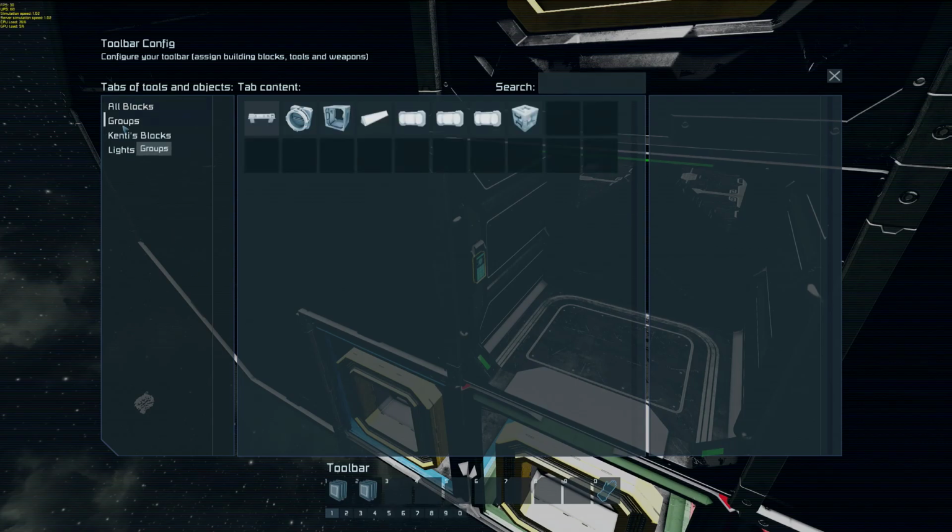So groups, in this case, we understand here warning and illumination. I'm looking for warning and illumination. So my red lights and my yellow lights specifically as groups really don't matter, even though I created groups to do that. What I actually did was took the two groups, put them together in one group, but there's a 50% offset on one versus the other. So it's really all within one group. I could delete those other groups and it wouldn't matter at all, but we'll go ahead and leave them in there.